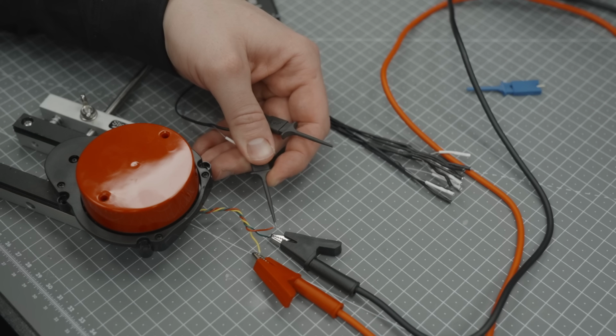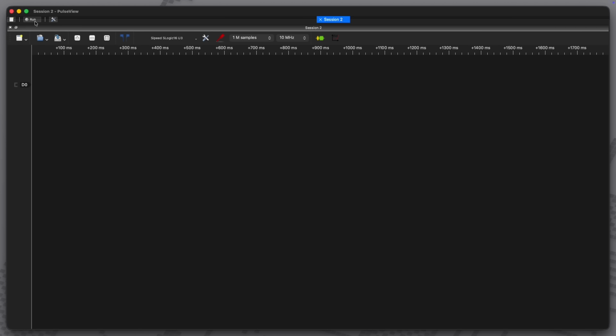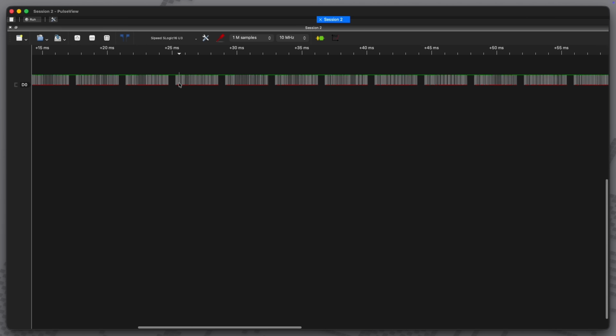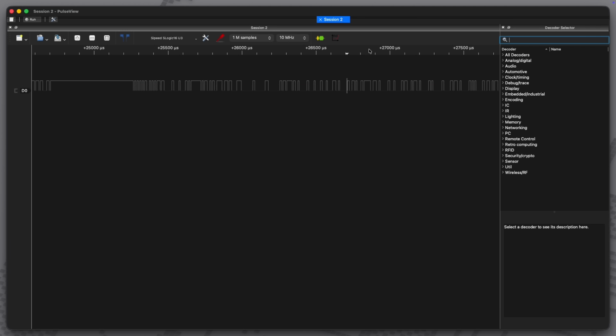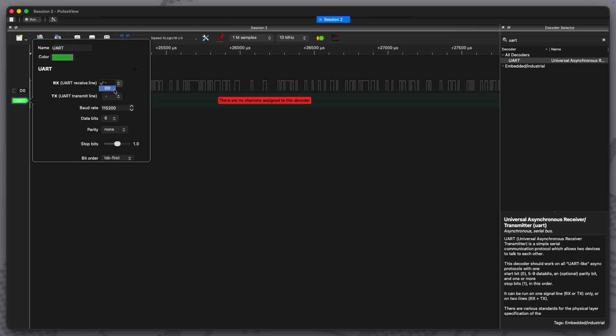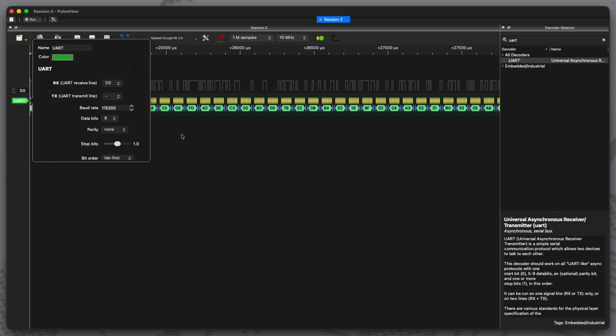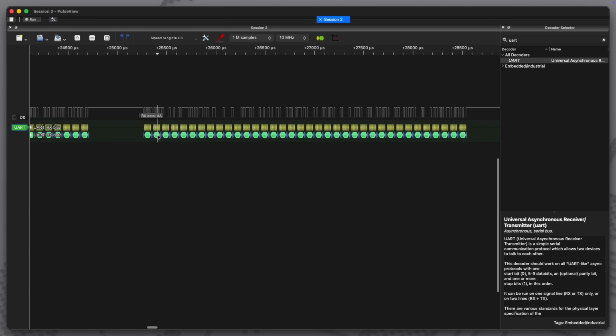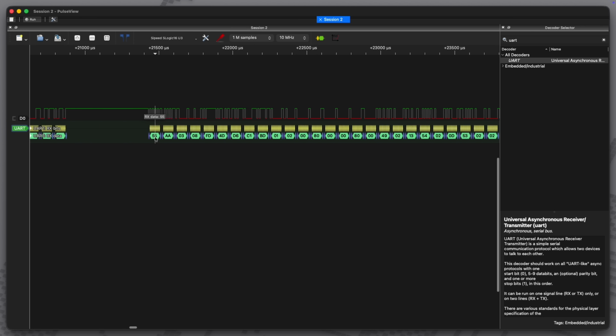With UART I always play around with the decoder settings until I don't get any framing errors anymore. Here it seemed pretty easy. A baud rate of 115200 with standard 8N1 settings seemed to make sense. Those chunks all seem to share the same starting bytes, which may be some frame header or so.